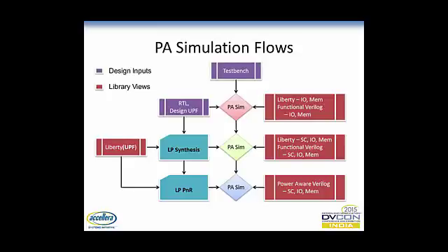Then you take the same netlist to PNR and do the implementation, where your power and grounds come into the picture, and those get translated into your netlist as well. Once the netlist is generated post PNR, you take it to simulation. You don't actually need the Liberty view, because Liberty captures your power intent, but now your netlist already has it.